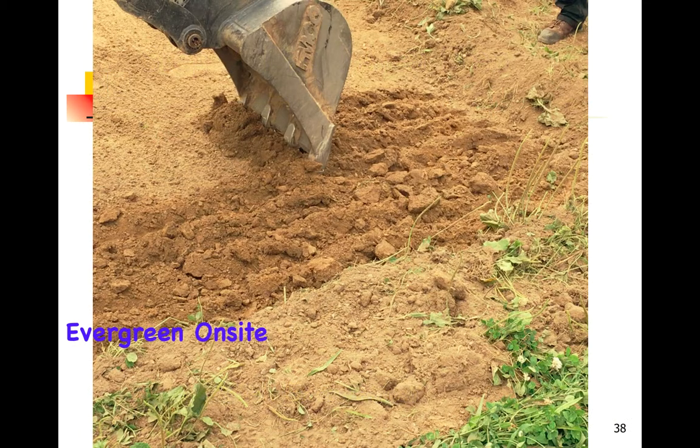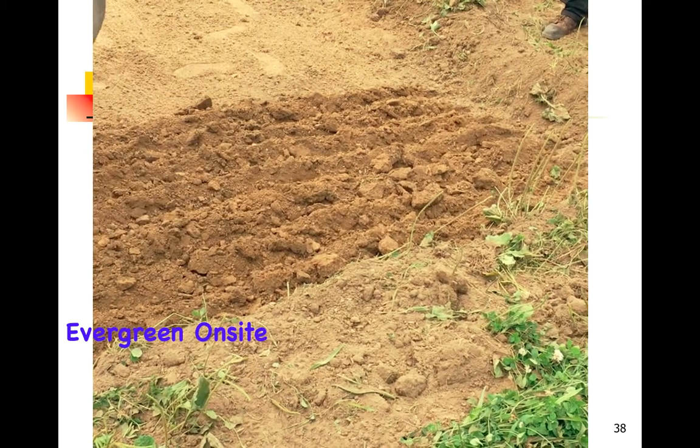In other applications, you'll notice here that they've actually excavated down to flatten the basal area. If you have enough soil, you can do this. It will lower the soil profile. Make sure that that's approvable either from your design criteria or at the local health before you make a field determination whether you want to remove soil prior to the basal prep. In any event, the basal prep itself is still very similar.